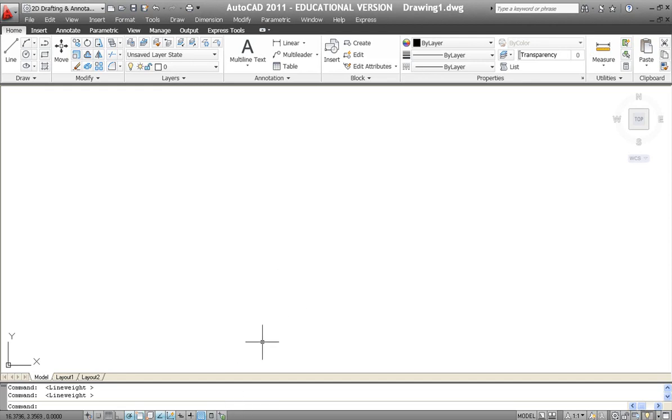At the bottom of the screen, what you're looking at is, if I just paused and came back, if this seems like it's discontinuous, that's why. The area down below is called the command line. This is something that is unusual in CAD programs. I like it a great deal, and most people who have been using AutoCAD like it a great deal, because if you're thinking, I'd like to draw a line, what would I do? You can just try typing the word line, and sure enough, if you press enter and something happens down here, it's a command.